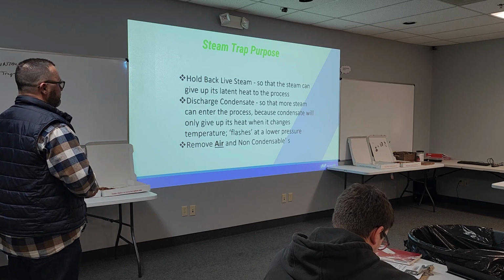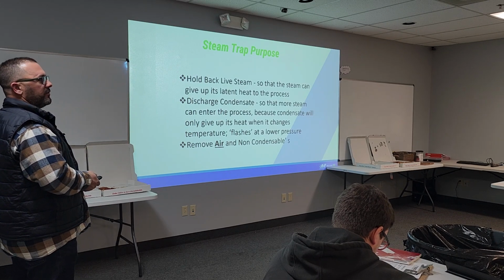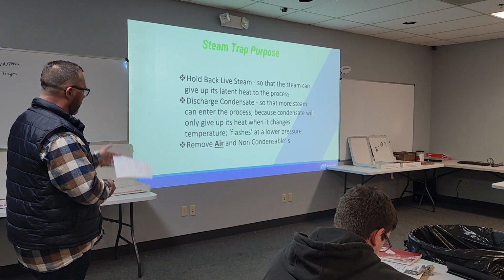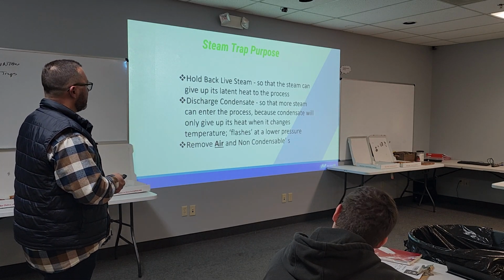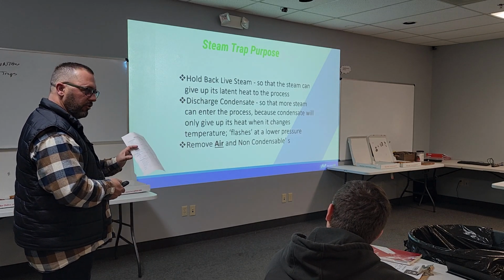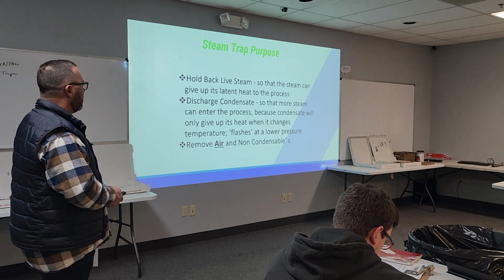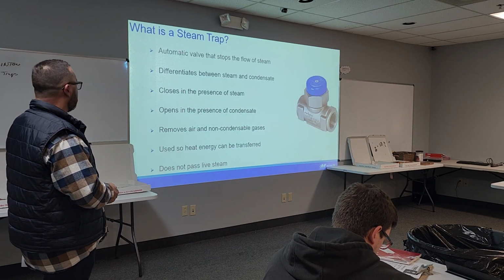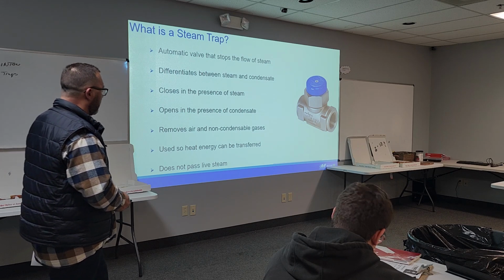And the trap that handles air the best is a floating thermostatic. It's got, and we're going to look at the animation here, a thermostatic air vent in it, and it by far handles air the most, and that's why it is a process trap.